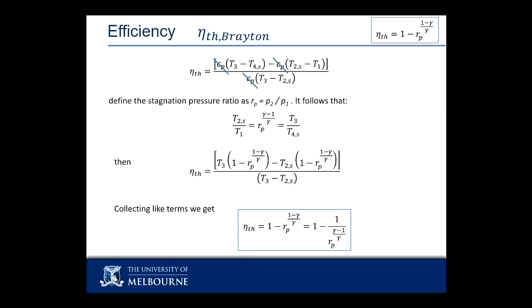What happens to my temperature? Every time I compress, my temperature goes up. If I set fire to something on top of that compressed air, it will get hotter and hotter. So there will be a natural limit to how big I can make these things, and that natural limit is once I've compressed and then set fire to my fuel, that final temperature better not melt the engine. So there's a practical limit to my compression ratios.